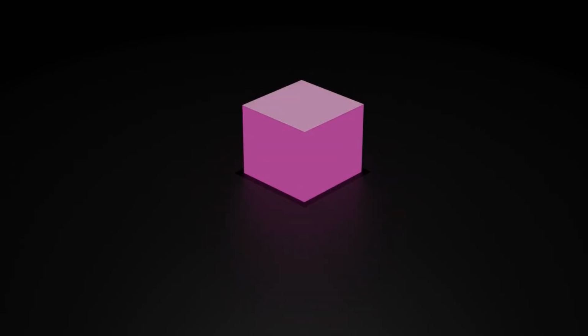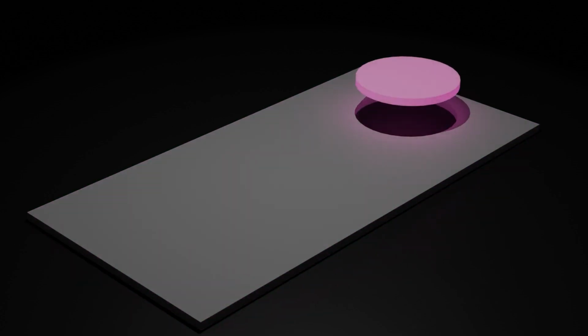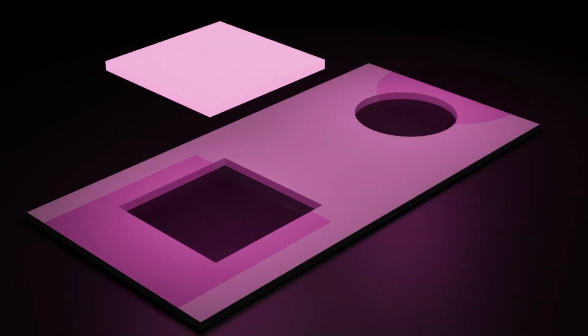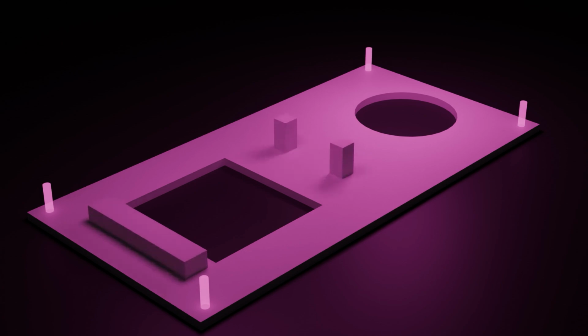And so with that in mind, let's begin with a cube. As always, we take the cube, flatten it, and change the proportions. Now we'll just cut out the circle for the joystick, and the square for the 8x8. This will be the face, where we'll use the joystick and the matrix. Next, we'd add some places for the screws on the corners to attach it, and some supports for the 8x8 and the joystick. That's because we don't want them to fall completely into the holes, we only want them to be in the right position, so that's why we need those supports.